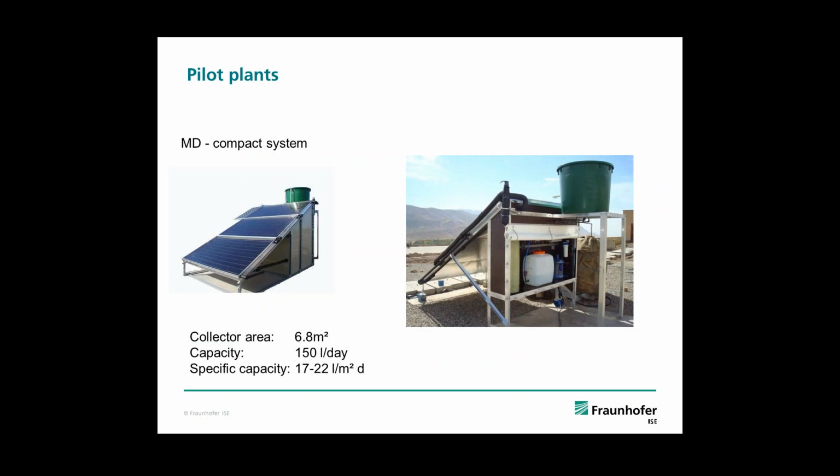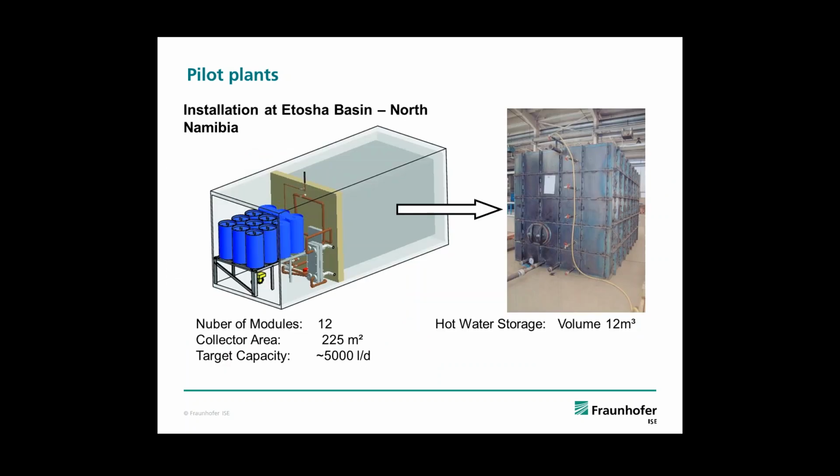So you can achieve pretty high flux values with membrane distillation, which are far above reverse osmosis. We can achieve 50-60 kilograms per square meter. But on the other hand, then the heat recovery is pretty poor. On the other hand, we can achieve very high GOR values of up to 9. But on the other hand, flux values are pretty low then.